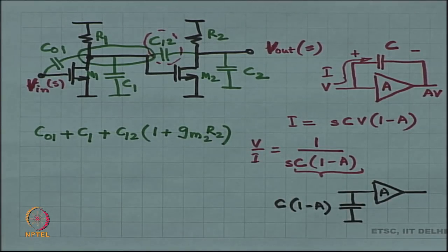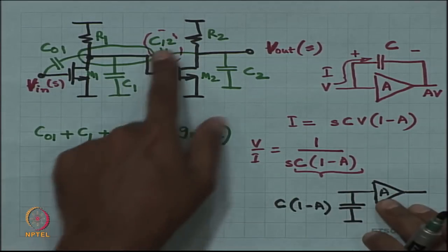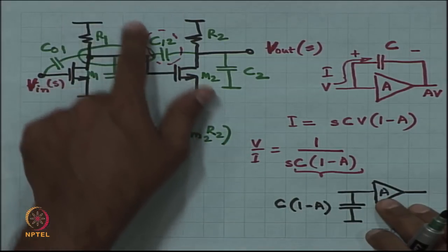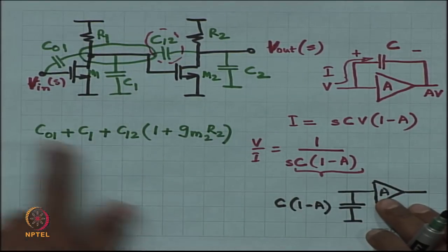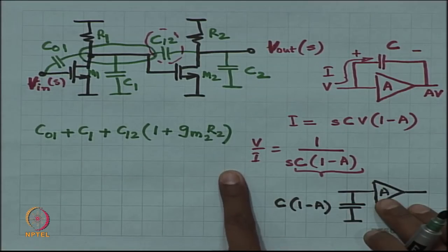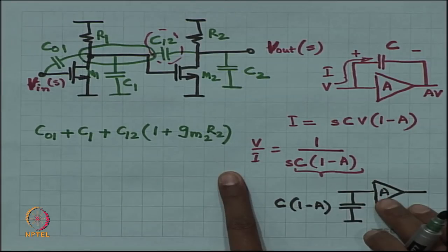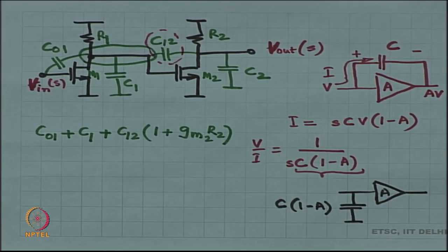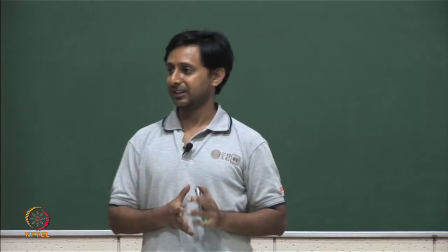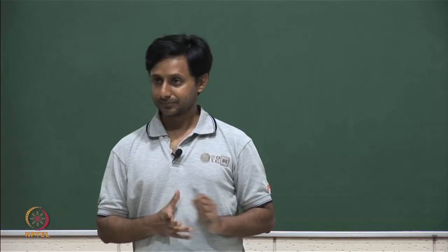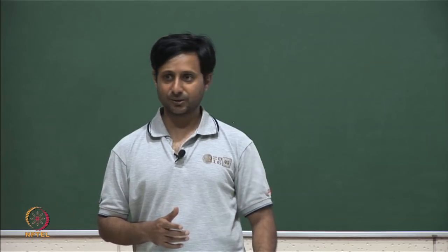Okay. And now suddenly the problem is tractable, right. Now suddenly you see that you have got a pole at R1 times this, all right. It is a much easier problem. Now this handle can also be used to engineer the two poles to be much greater than one pole, much greater than the other. Okay. So, some engineering also can be done over here.